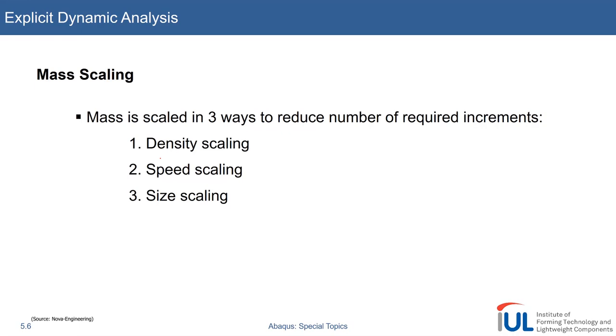It's called density scaling, which is classically called mass scaling because density times volume, and so on. But usually nowadays mass scaling encompasses these 3 things, of which the latter one, I've never seen anyone except me actually using this. Maybe I'm a weird dude, but I don't know if I invented this.